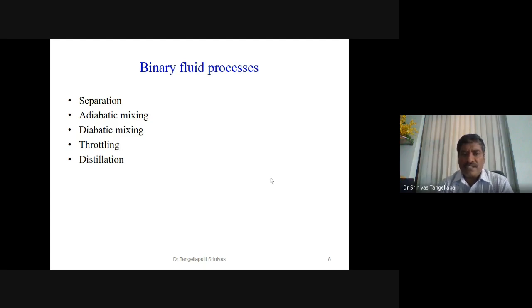So these three components, that's condensation, throttling, and evaporation, are common to both the vapor compression refrigeration system and the vapor absorption refrigeration system. The remaining components like distillation, separation, absorption, pumping, boiling are different. Okay, in the distillation, we are going to increase the concentration of the fluid, so that will favor the cooling system. How it is favoring the power system, I will explain later.